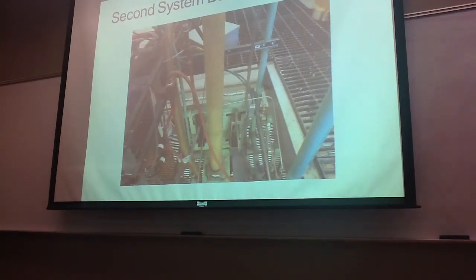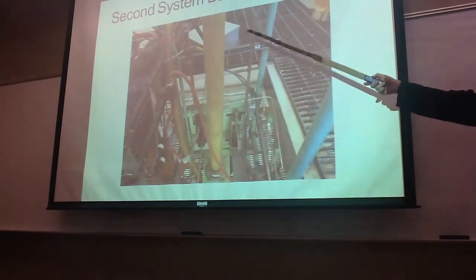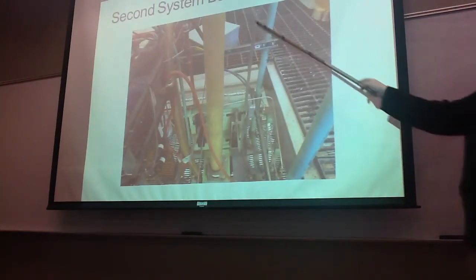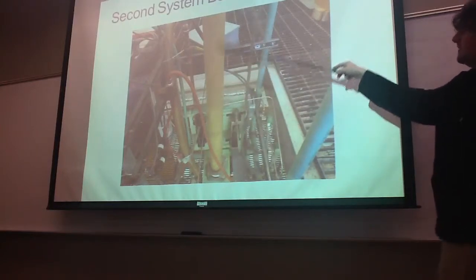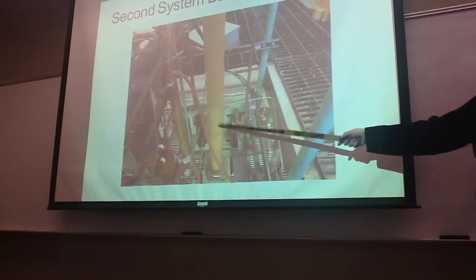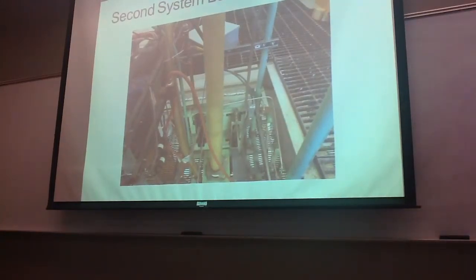What you do is you take your nasty gas and you push it up through this pipe. And then you take your water or other liquid in which it dissolves and you let the water flow down as the gas flows up. And this pipe is filled with stuff. It's filled with packing. And this packing is designed to block the flow of the water and move it around to increase the area of reaction between the gas and the water, so that you can get the maximum amount of absorption of your nasty gas into your water. And that's all fine and dandy. Just thought I'd talk about that.